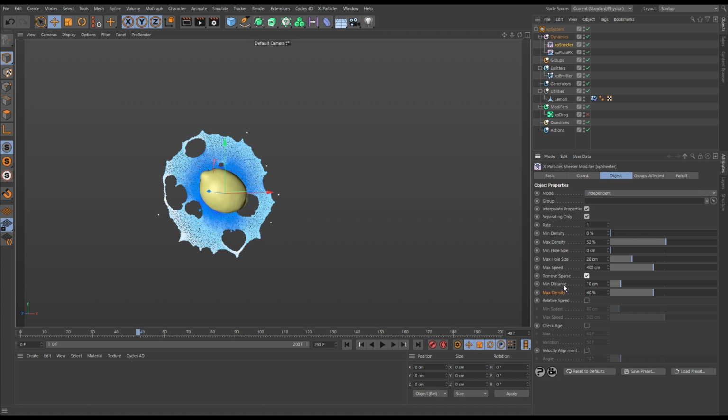Now there are two checks that are done, two sliders to set for this. The first one is a minimum distance, and what it says is this: it looks within this minimum distance of 10 centimeters, and if there are no other particles within this minimum distance, then it considers itself a sparse particle because it has no friends within this minimum. So therefore, if it is a sparse particle, it is a candidate for being deleted, but it then has to do a density check first.